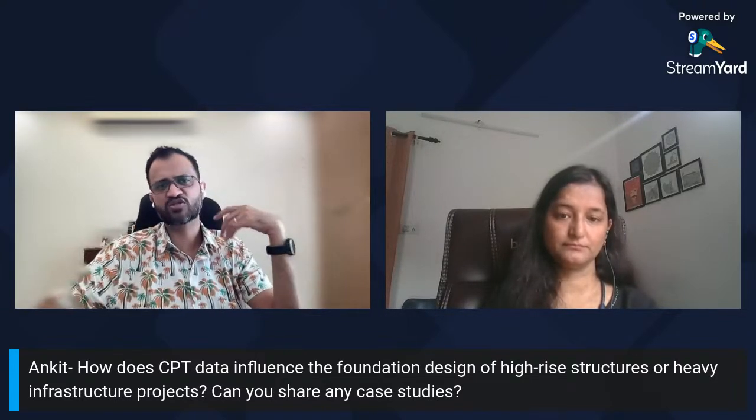Question from Ankit. How does CPT data influence the foundation design of high-rise structures or heavy infrastructure projects? Can you share any case studies? That's a good question, Ankit. In the next part of this presentation, part two, we will be talking about CPT interpretations, as well as how you can calculate SBC based on CPT data. But to answer the question in short, how does CPT data influence the foundation design? It doesn't influence. It's just another data, right? You just get more data for your foundation analysis.